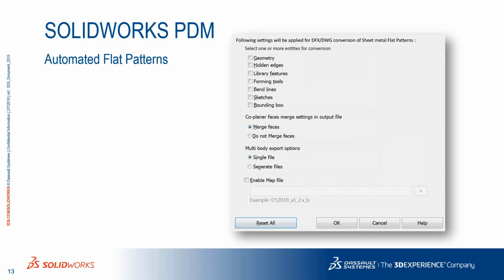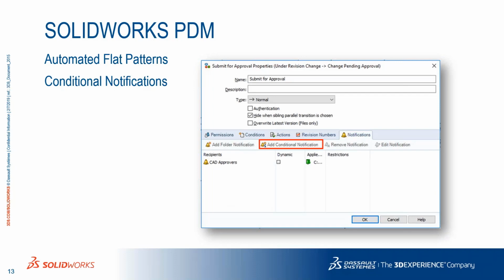A few other things more on the administrative side, I guess, with SolidWorks PDM for 2019 is the automation tools. They are great with the workflow and being able to automatically generate PDFs, DXFs, automatically send out notifications as a product goes through a workflow. But now they've added one more little capability in those automatic transitions and tasks that are run, which is being able to run an automatic flat pattern of a part to be able to export a DXF or DWG of the actual flattened state of the part as a file is moved through the workflow. So oftentimes this will be when a file gets released to get a major revision incremented on it. We'll see not only a PDF generated, but also now automatic DXFs for flat patterns that you can send out to get those burned, automatically generated. Again, just a couple clicks, little bit of work that nobody has to remember to do. It just gets done automatically as the file moves through the workflow.